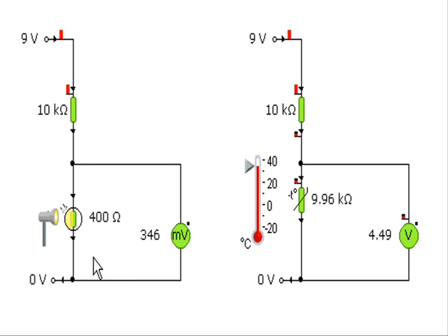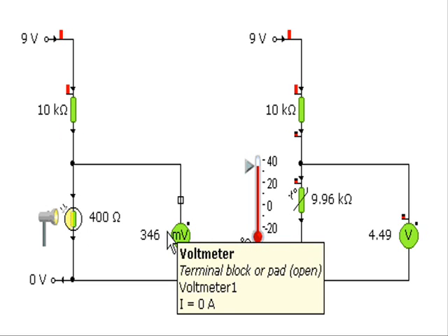The LDR's resistance is big in the dark. Right? So it's a big resistance here, 1 mega ohm, and a smaller resistance up here. So this is taking a bigger proportion of the voltage. So the big resistance takes a big bit of the voltage. Okay, when it's smaller, it takes a smaller bit of the voltage.